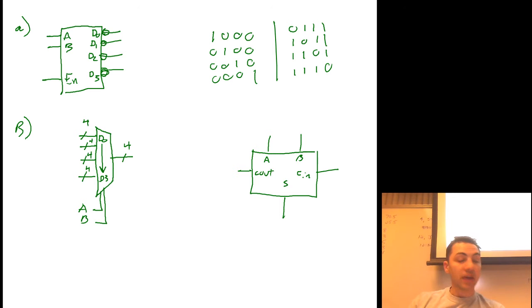A 4-bit full adder would have 4-bit inputs and 4-bit outputs. It would not have a 4-bit carry out or a 4-bit carry in. It's a single bit carry in. If you put your carry outs at the bottom or your carry ins at the top, I don't care, as long as those pieces are somewhere on that module.